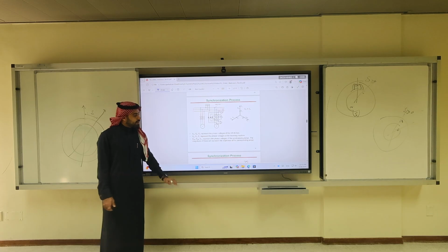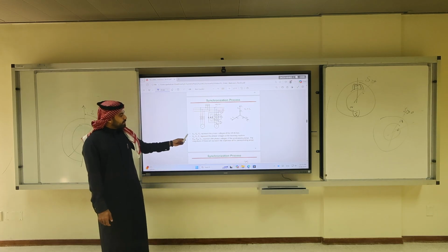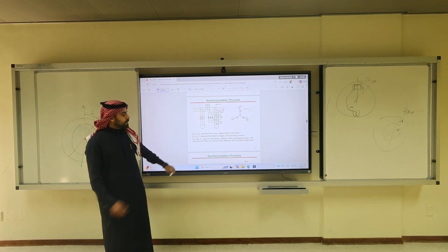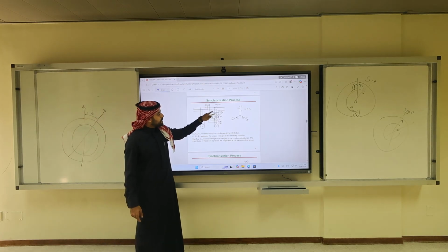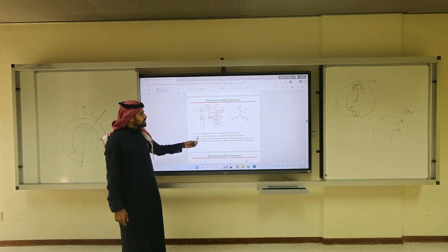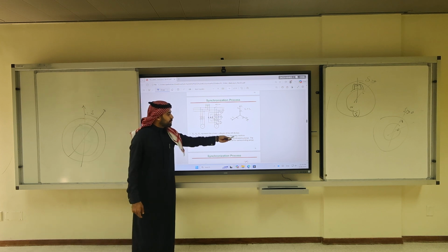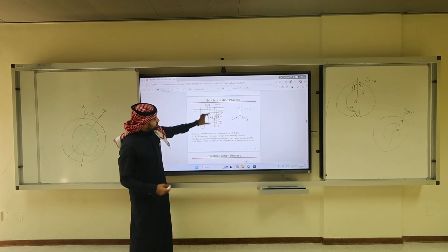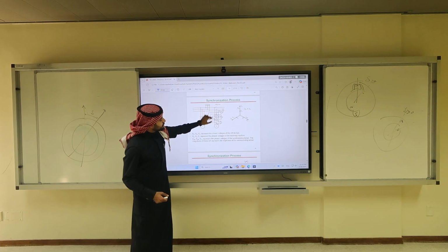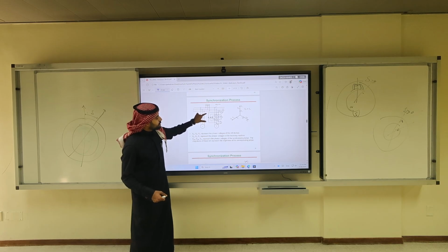You will do this in the lab. So here we have EA, capital B, capital C. These are the voltages for A, B, and C, the line or the infinite bus. The small letter is for the incoming machine. EA, this is capital A minus small a, which is basically the voltage drop between capital A and small a, is the light bulb 1, light bulb 2, light bulb 3.